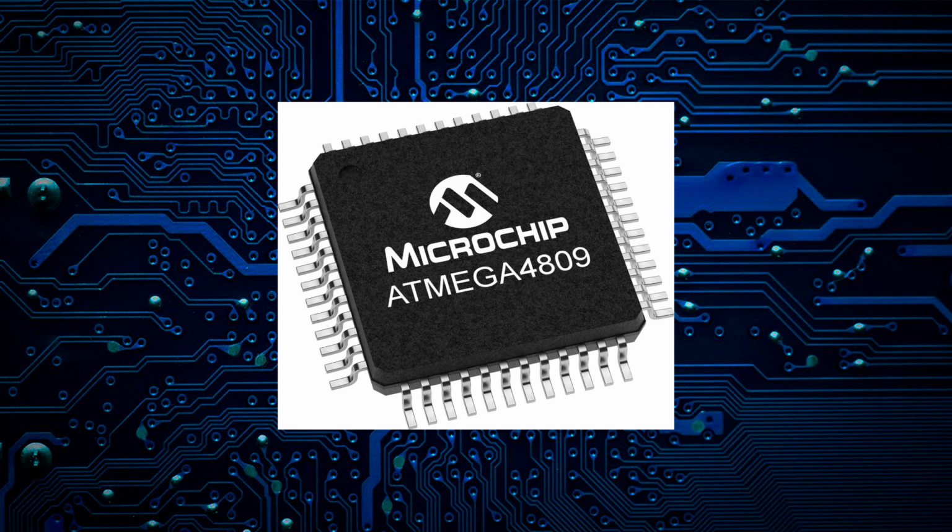In the case of microcontrollers, most of them have a PWM peripheral. When microcontrollers have this peripheral, it's very easy to generate a PWM signal, because we only need to manipulate the registers of the peripheral and we have an output. For this case, we will use the microcontroller ATmega4809 that has a 16-bit timer and allows us to generate an accurate PWM signal.